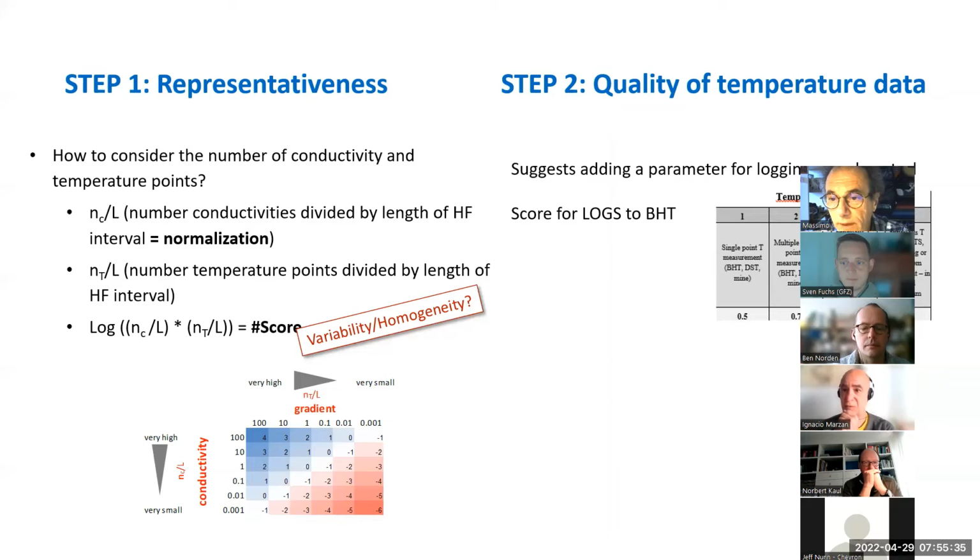Oh, Massimo, yeah. How is this DST measurement? Oh, it's a specific test that is performed in oil exploration. After drilling is completed, the borehole is first put under pressure, and then pressure is released, and the oil or gas flows up to the surface in a very, very short time, and the temperature is measured.